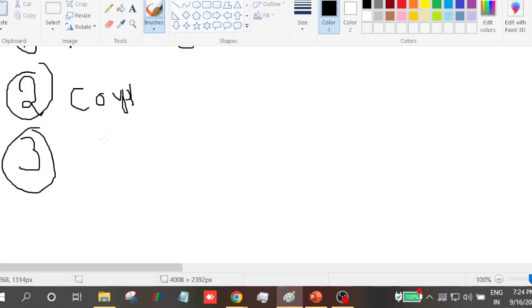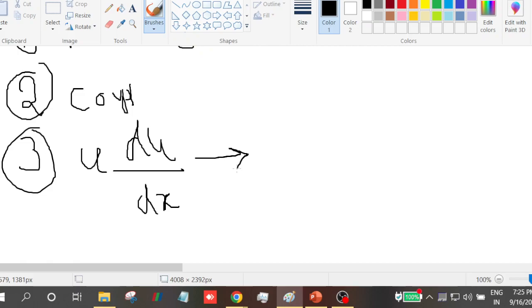We usually have in the advection term u du by dx, in the x momentum, say. Now you can understand that when we do the discretization, you will end up with u square, ui square or ui into ui plus 1. So basically u square comes into the picture, which makes the equation non-linear in nature. In order to avoid this non-linearity, we lag this by one iteration, or if we are doing transient simulations, we take it from the previous time step.